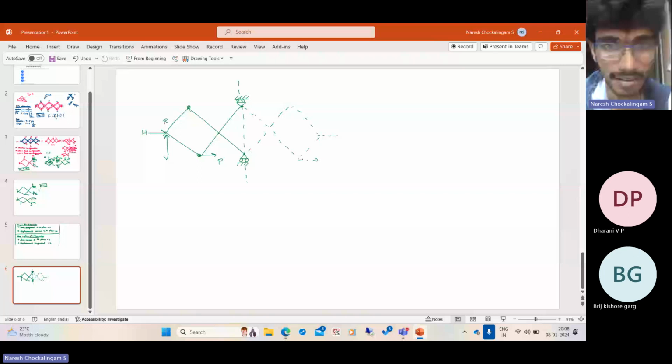So if you see, H is equal to minus P, right? Because here there is no horizontal force, here there is no horizontal force. This force is vertical, and the question is to find only the horizontal forces. So from this loading, you got H is equal to minus P. So if I draw the correct sign convention, P, and here it is a compressive force of P. Done. So from part B, we are getting the horizontal reaction at S equal to P towards the left.